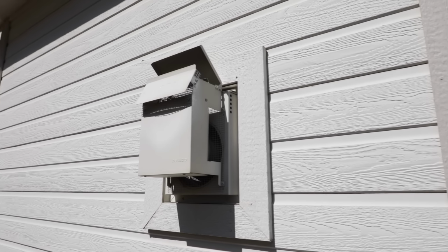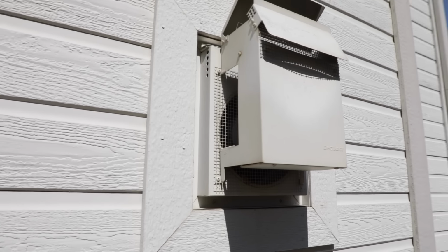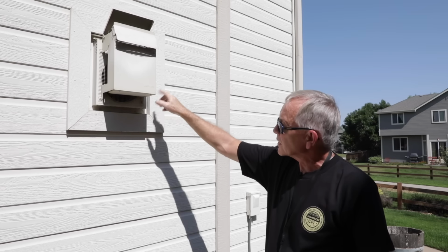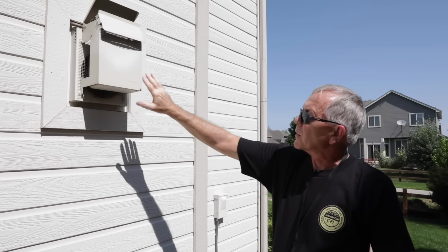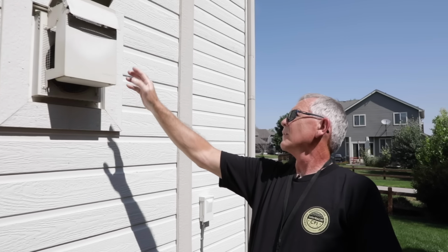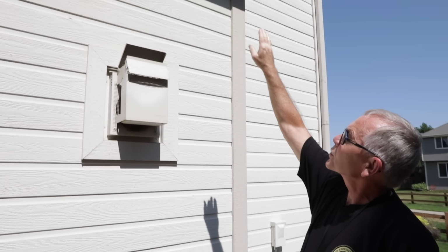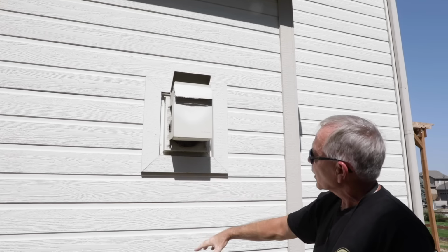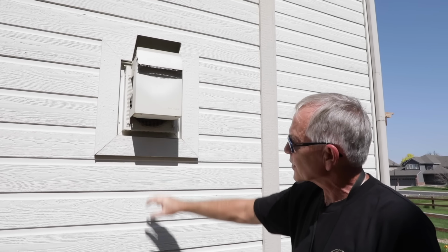I can tell that this is the chimney and chimney cap for the fireplace. I've been inside already. The fireplace is behind this. I believe that this is going to be a B vent type vent pipe on here. So make sure you watch out for this and note any damage, possible clearance issues with the eave above. Look for black spots where you might have some incomplete burns where it put a lot of soot out here on the siding.